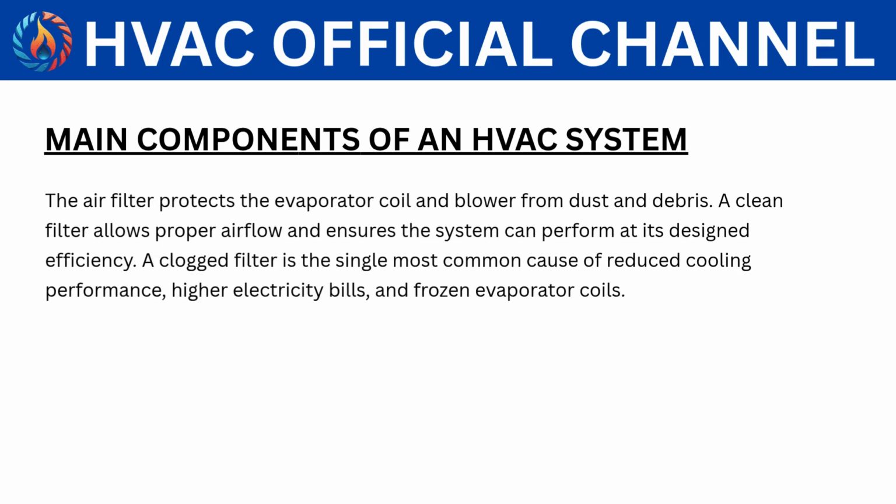The air filter protects the evaporator coil and blower from dust and debris. A clean filter allows proper airflow and ensures the system can perform at its designed efficiency. A clogged filter is the single most common cause of reduced cooling performance, higher electricity bills, and frozen evaporator coils.